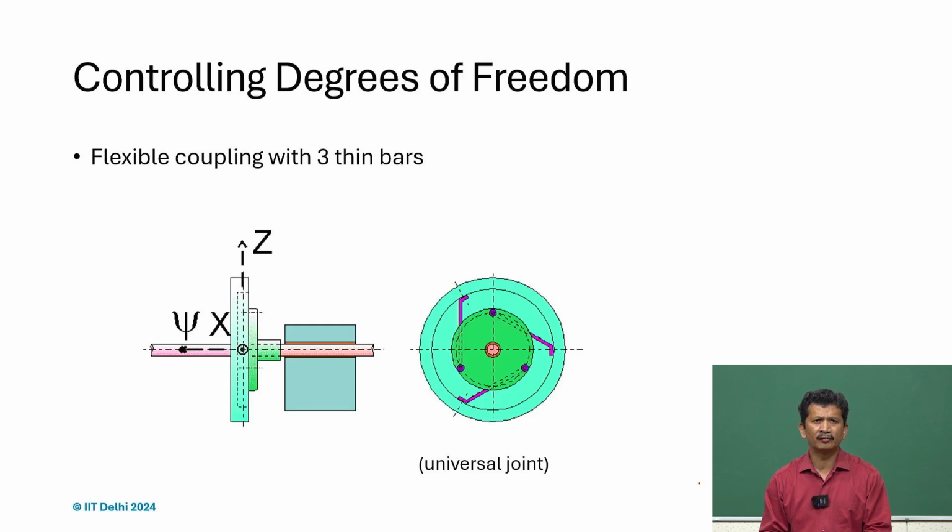So, what happens if you are looking for high speed applications? It may not be very good, because some eccentricity will always give rise to a lot of dynamic loading, and then we will have a lot of vibration. If you want to address that, then we are looking for symmetric solutions, like what you see in this case. Although it is an over constrained design, it is symmetric and flexible, so it can be accommodated easily.